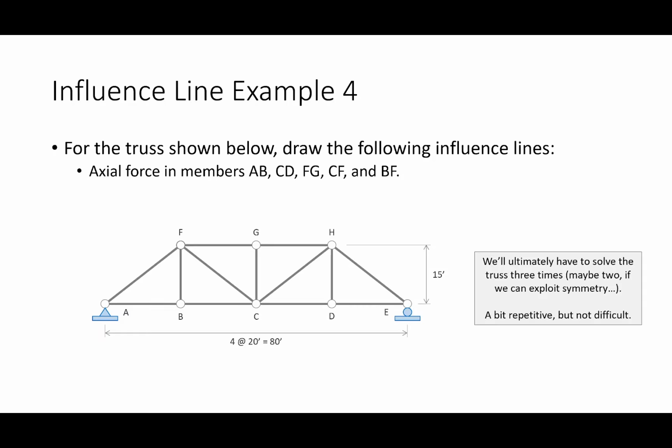A and E. Because if I put the load at A or I put the load at E, what is the internal response inside the truss? 0. So that's done. The rest, though, we have to deal with.